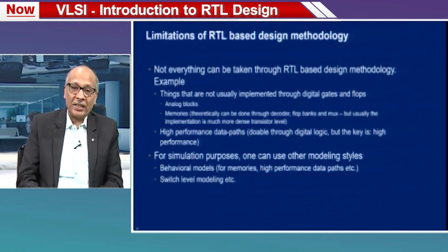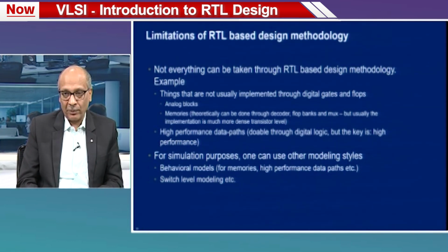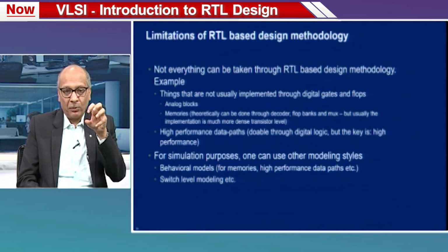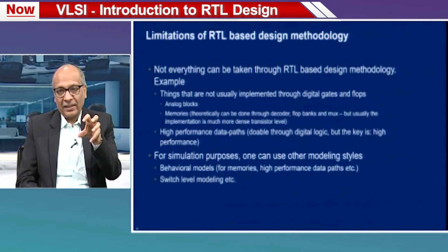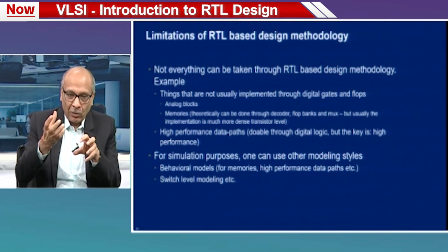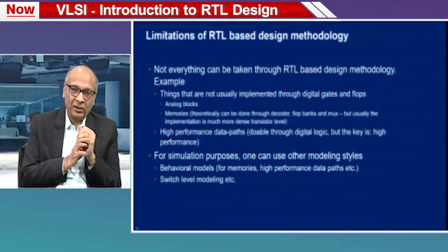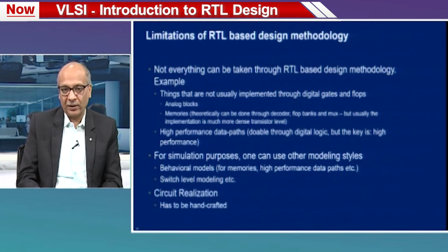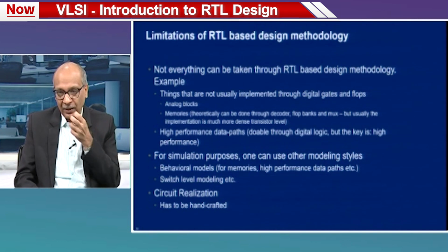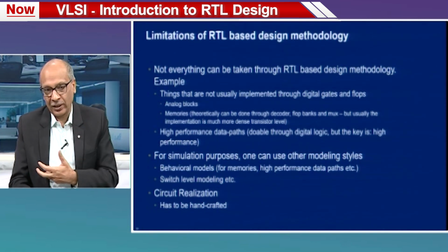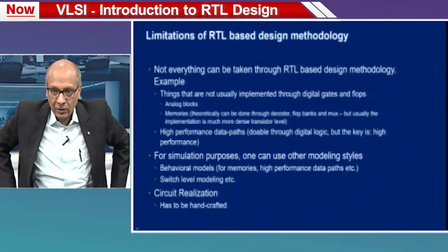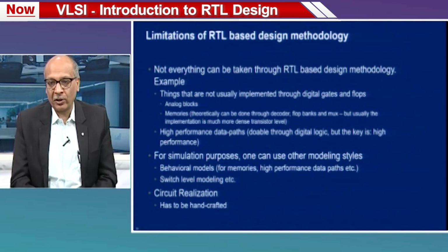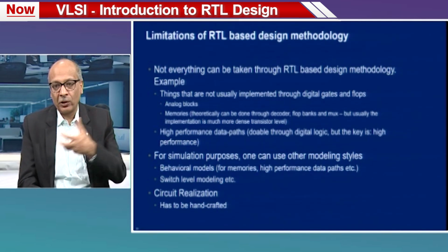So what do we do about these kind of blocks? These blocks which don't lend themselves to RTL based design methodology. For simulation, we can still write, say, behavioral model or switch level model, etc. And for circuit realization, it has to be handcrafted. We cannot use synthesis. RTL we had used for simulation and for circuit realization, but for these kind of blocks we'll write behavioral models or switch level model or whatever, and realization we'll do through handcrafting.